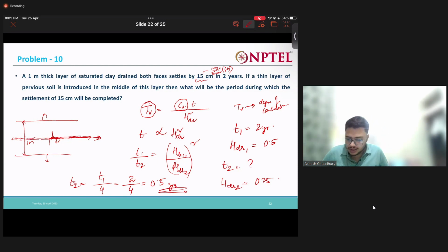right? So you are increasing the drainage, our time reduced from 2 years to 0.5 years. Okay, so that's why it's very important, in order to accelerate the process of consolidation, we need to increase the drainage. Yes, time reduced by 4 times.